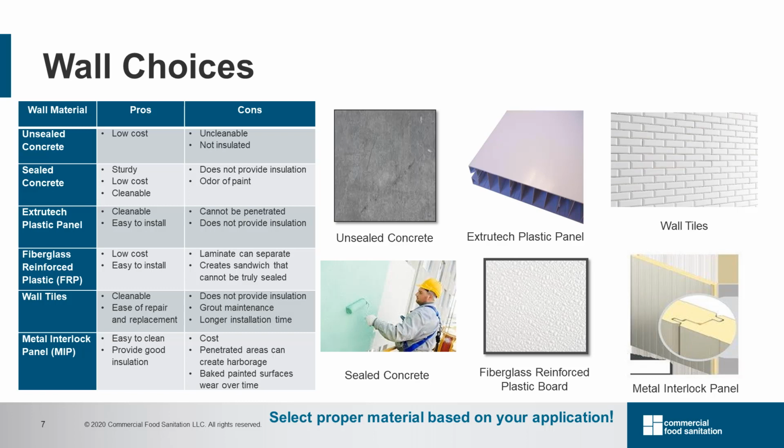The surface of the metal insulated panels is smooth, easy to clean and has good insulation. However, due to the sandwich structure, it is easily damaged by hitting and therefore should not be penetrated. The joints of the plates need to be sealed during installation.